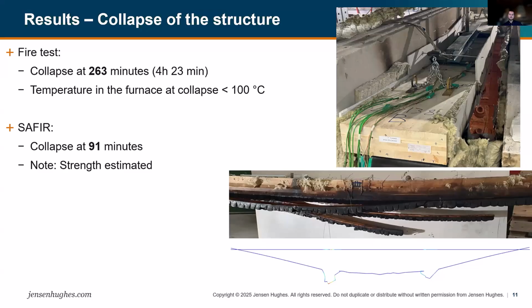In SAFIR, on the other hand, we had collapse at 91 minutes, so very notably a shorter load-bearing time. But note that the strength in the model was estimated because we did not have an exact value for the strength of the slab.